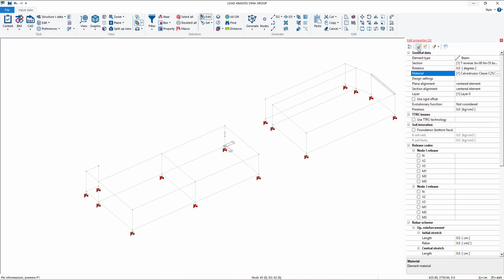So my suggestion is to keep this always activated. Once you change something, okay, let's say that material is number 2, the property that you change are going to be highlighted in black, it's going to be bold, and then you click on this set properties and apply. Click it a couple of times to be sure that the program received the command.